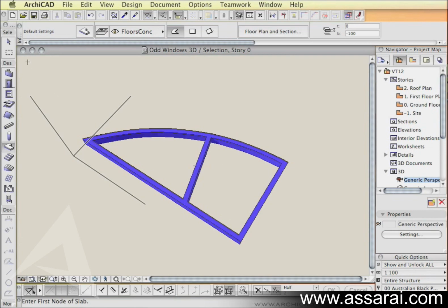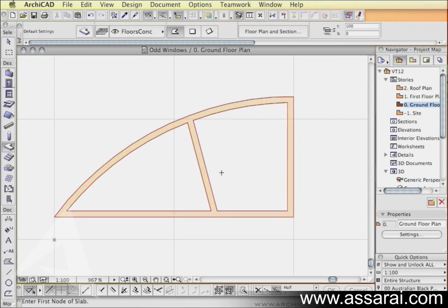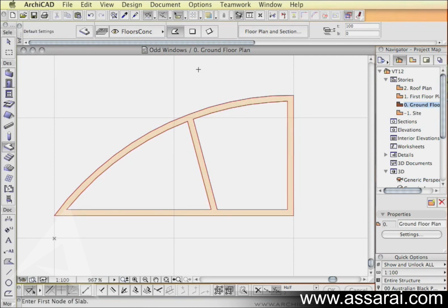So now we've got this. This frame is 50 by 100, 100 comes from up here, and the 50mm comes from the sketch that we created. The next thing I'm going to do is to again use the slab tool, but this time I just want to put glass in, so I'm going to change the bottom to 50, so the glass is halfway through the frame and the top can be 60.